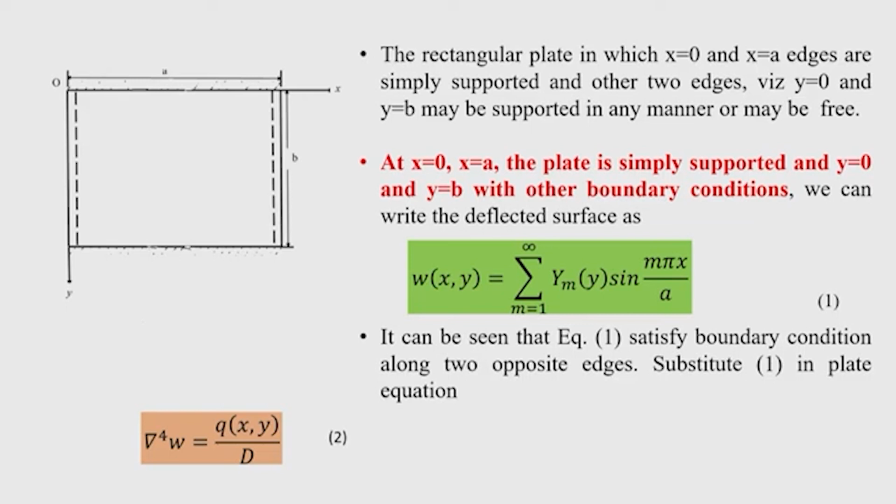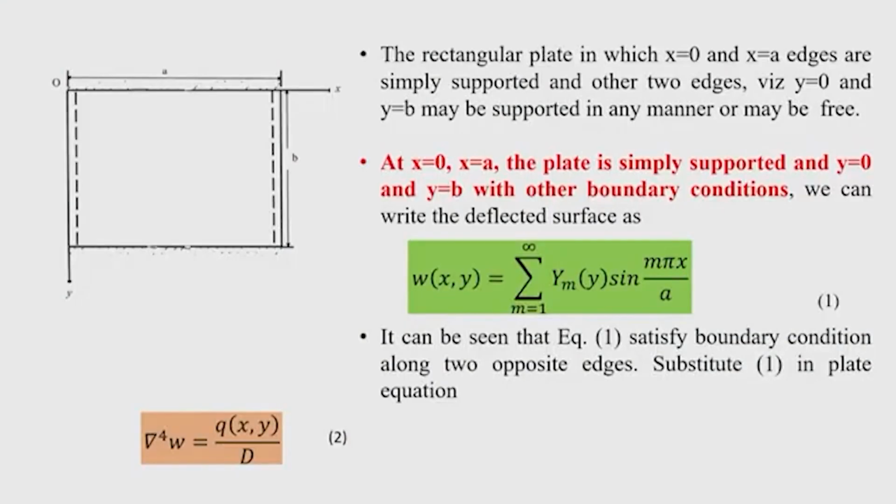Now, one thing can be noted here, that while solving the differential equation we have taken the uniform thickness of the plate. Therefore, D is not variable in x and y. That is the characteristic of this differential equation. When D is variable, then the plate equation will be complicated and different techniques have to be used.